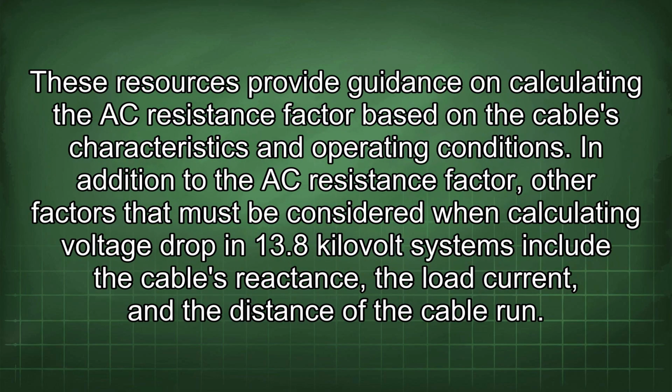These resources provide guidance on calculating the AC resistance factor based on the cable's characteristics and operating conditions. In addition to the AC resistance factor, other factors that must be considered when calculating voltage drop in 13.8 kilovolt systems include the cable's reactance, the load current, and the distance of the cable run.